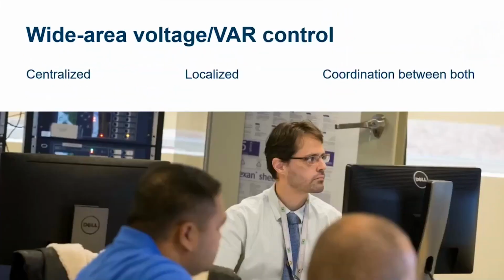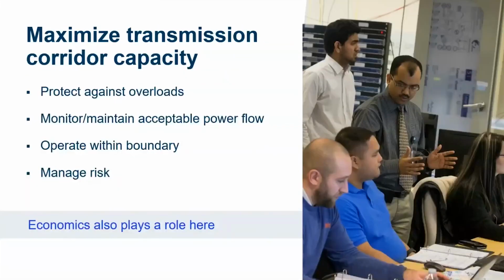For example, for voltage regulation, we may decide to take an action to turn on line reactors after performing load generation rebalancing. But there can be a localized control to control that reactor bank, or on-load tap changers, or static var compensator or other var compensating equipment. There is an inherent need for centralized and localized control and a coordination in between for a successful system operation.